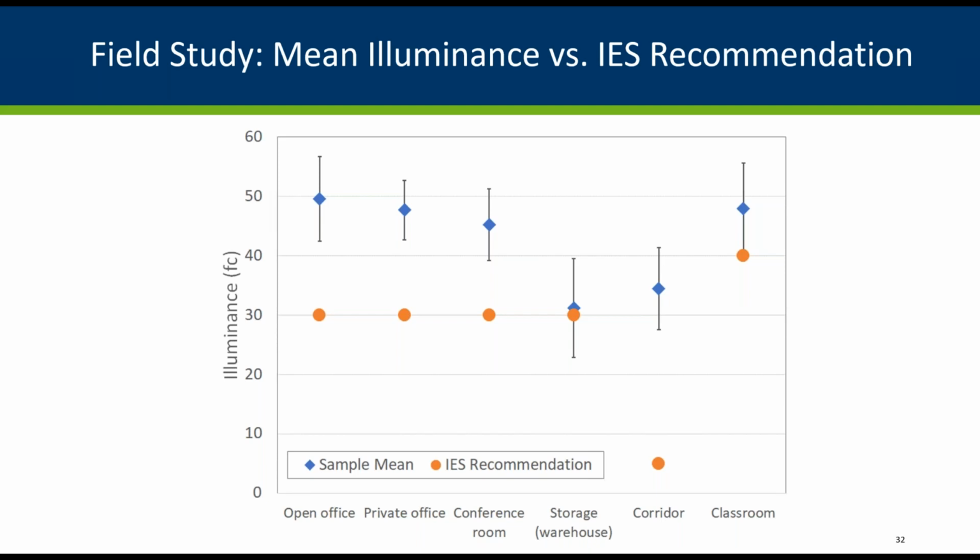When multiple lumen packages exist for LED replacement fixtures, lighting professionals and contractors tend to default to higher lumen packages to minimize the chance of customer dissatisfaction from low light levels. This default position is made even more reasonable given that the replacement fixtures will still yield significant energy savings. This systematic overlighting of LED retrofit spaces represents a significant opportunity for programs to address.